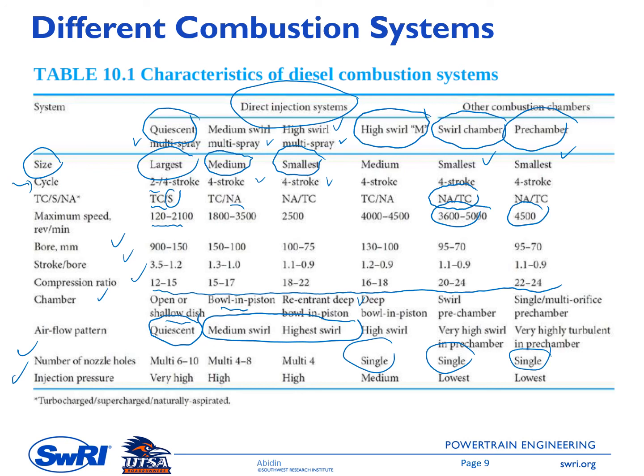So to enhance the atomization process, we need to have a very high injection pressure compared to the medium and small engine, which usually have a smaller nozzle size. And then on the next one you can see in here also the injection pressure for the indirect diesel injection system.